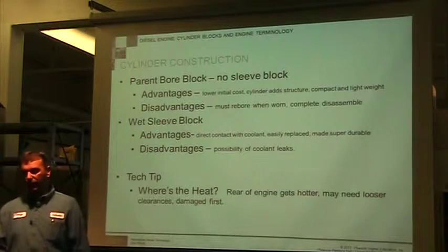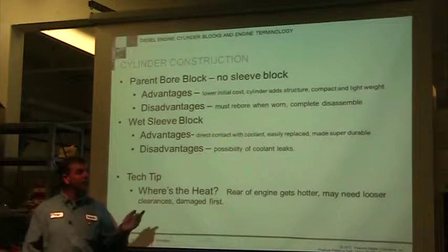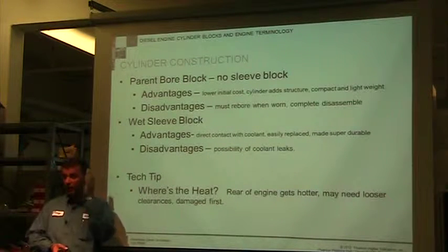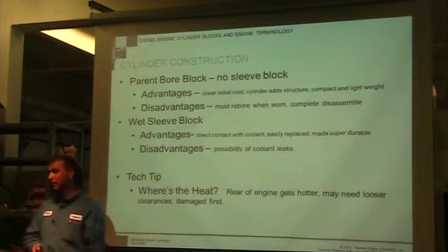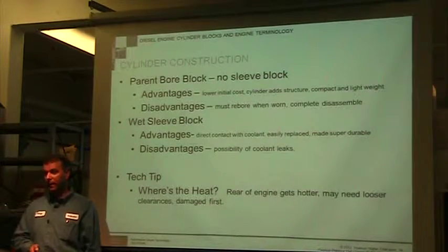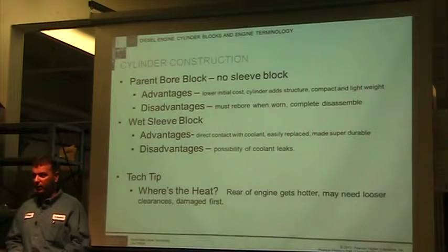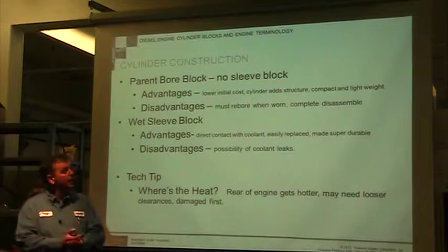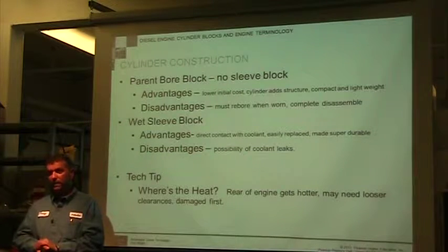Now, stepping forward to today with today's emissions, we already talked about the fact that if you're going to rebuild an engine today, it has to be 100% back to manufacturer specification. Well, reboring is not going to be possible if you're going to bring it back to manufacturer spec. You'd have to use a liner or something that would bring it back to spec. But they're also looking at all the other things that you have to bring up to spec.